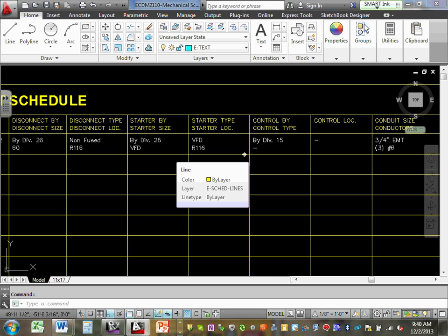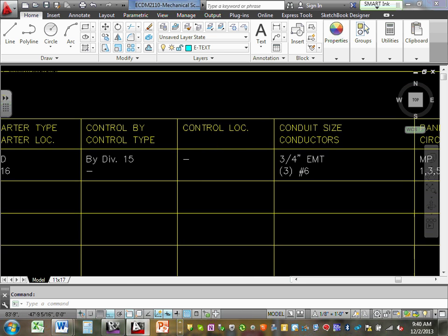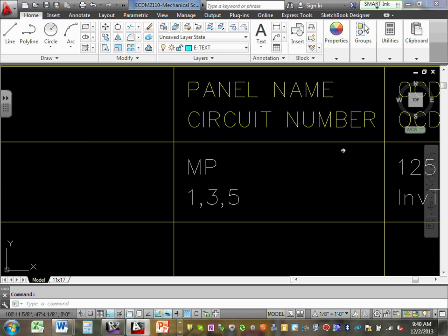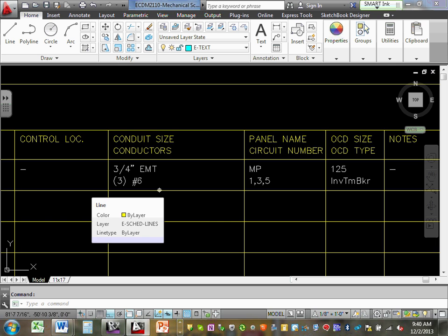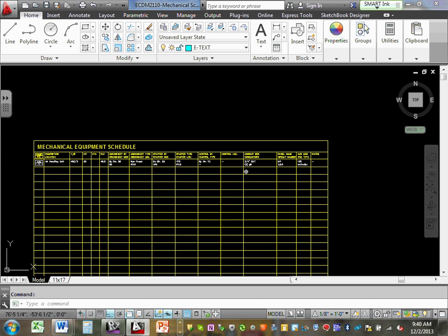Well, if you guys want to write yourself a note, very easy. When you're sizing, the overcurrent protection device is always 2.5. When you size the conductors, it is 1.25. When you size the disconnect, it's going to be 1.15. These are the ones that you learned in the calculation with your friend Chad. So we're done with this equipment.